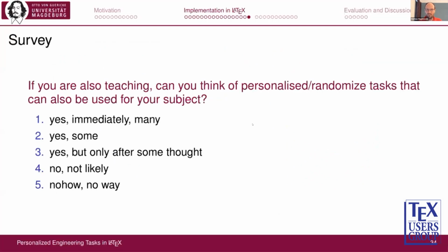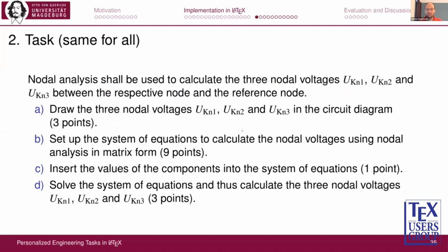So let's have a short look at a second task, and the second task is about nodal analysis. This is something in electrical engineering, a method to calculate all the voltages, and from the voltages and later on also the currents in a given circuit.